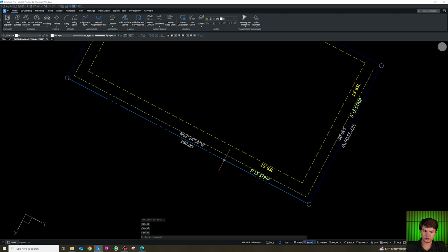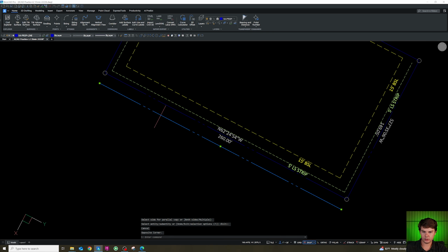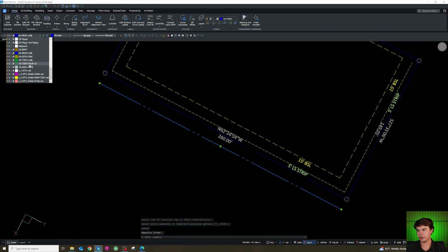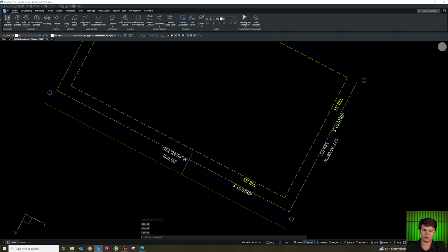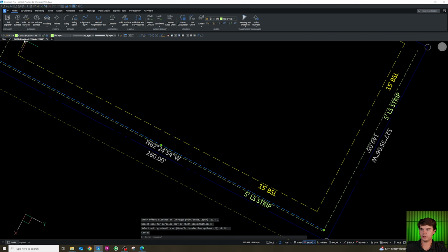Our primary constraint is going to be this, or we'll put in our existing road, which is 11 feet from the property line, and this will just go on the existing concrete layer. This will be our primary constraint, our main worry of encroaching, so we'll offset it 1 foot. Put this on the 0 layer.